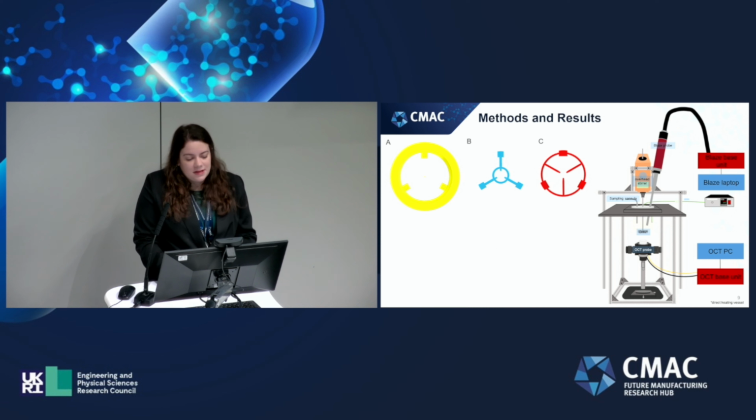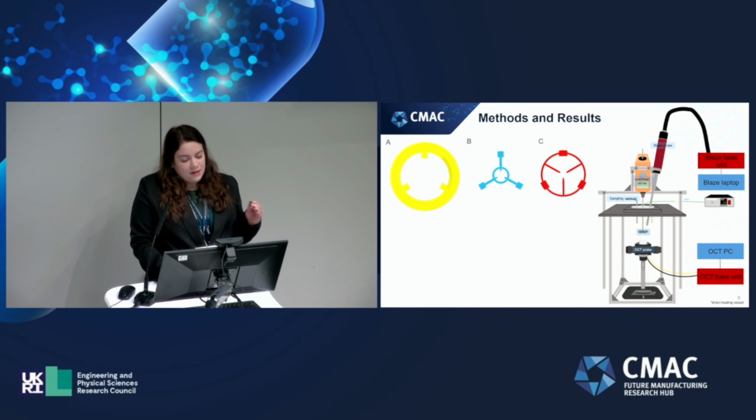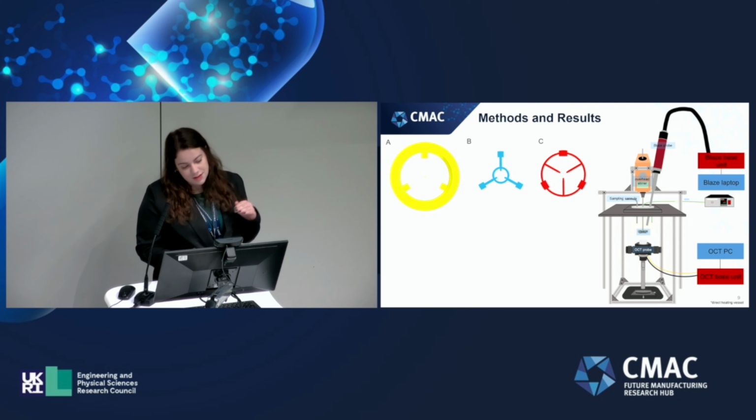One of the key things we wanted to capture was tablet swelling data and disintegration mechanisms. To do that, we had to hold the tablet off the bottom of the vessel because the imaging is coming in from underneath. So we developed this 3-part sample holder held together with magnets. I think it's important to note that we did a lot of work to make sure the impact of this was minimal on the tablet behaviour.